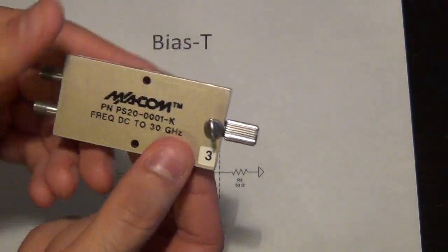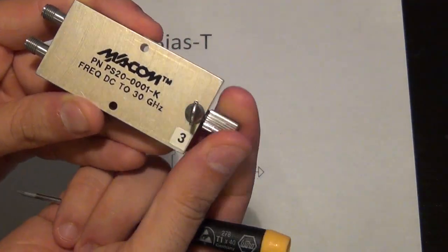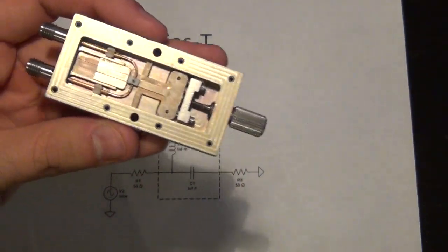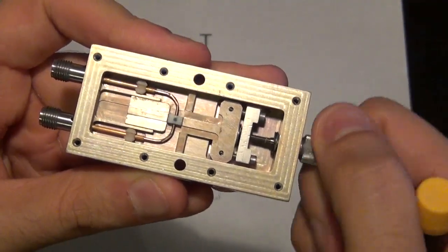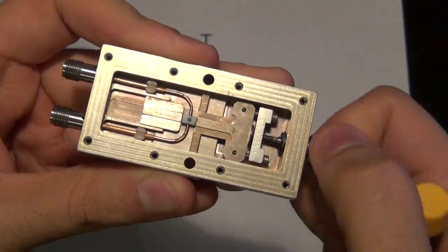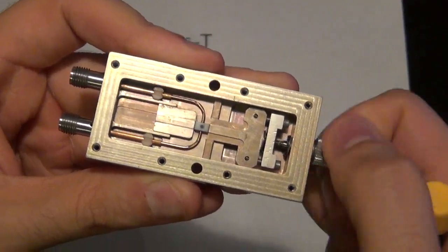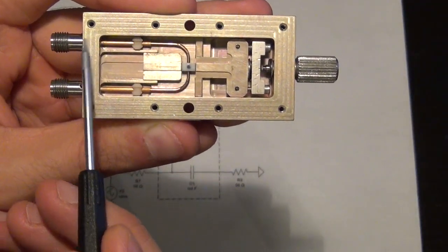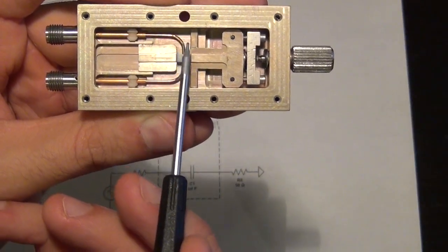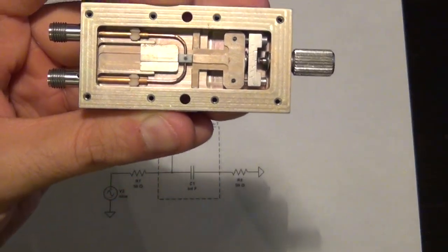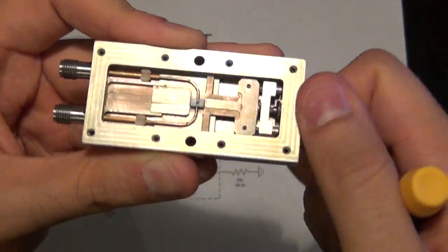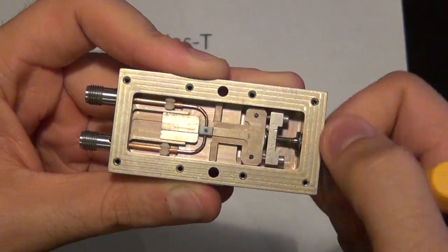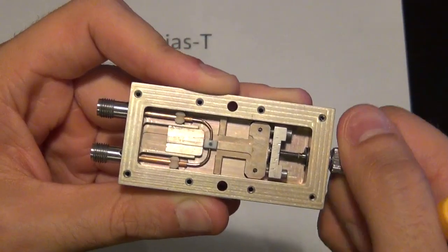And if I have it in a controlled way, I can have a phase shifter like this one, which is controlled by this knob. I've taken this one apart. There we go. You can see inside it. Now if I turn the knob, you can see that that plate moves back. Let's say I move it all the way back, and the signal now has to travel a longer distance. So the signal has to come all the way through here, goes through this wire and all the way back. And if I turn it the other way, I will shorten it. So now there is less distance between those two paths. So therefore the phase shift is less.